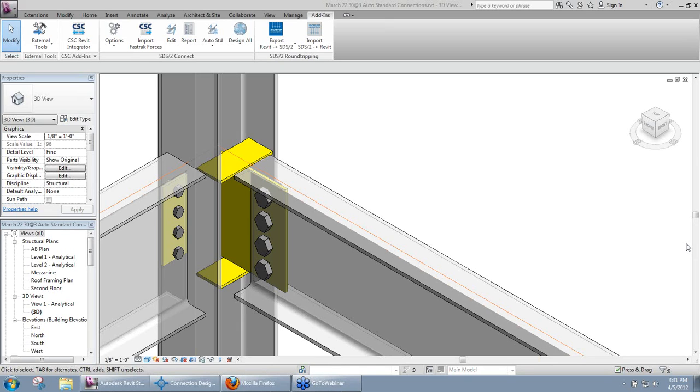Another question then, is Design Link required to transfer from Revit to SDS2? The answer to that one would be no. If you're using the round tripping included with this, which we see up on the toolbar here, you can actually import and export the models using basically the same functions in SDS2. It's actually found under your model pull down, and then there's a Revit section. That is only available in SDS2 versions 7.243 and higher. So anything lower than that version, it's not actually available in.